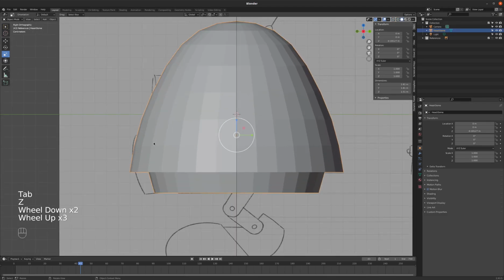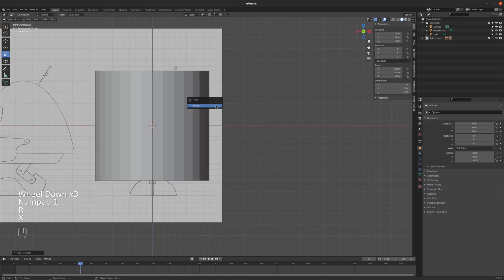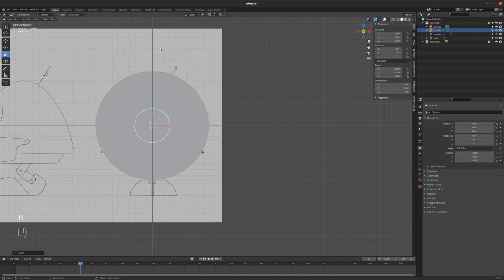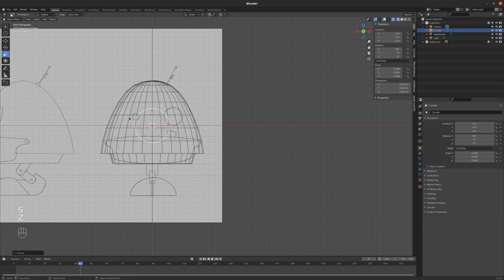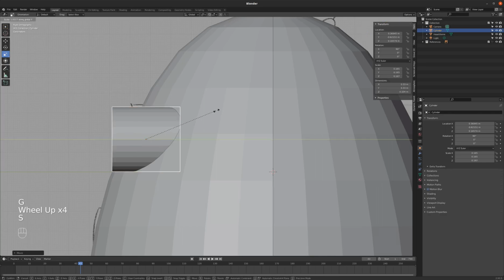There's the base object of the character, and now I am free to model the rest of it. I'm going to add a cylinder for the eyeball here, rotating X by 90, whoop, and it got added to the references collection again. Okay, I need to watch for that. RX90. We'll scale this thing down, and I think it probably has an n-gon cap by default because I didn't change anything, but we're going to end up deleting all of that anyway. So I'm not too concerned about it, and I'm just going to scale it in the y-axis.